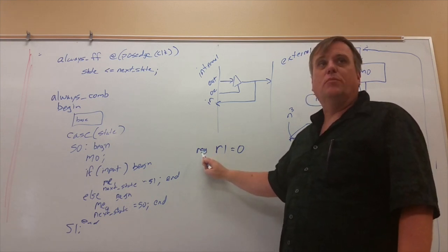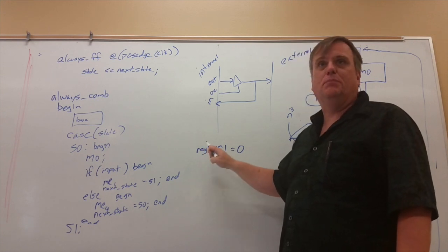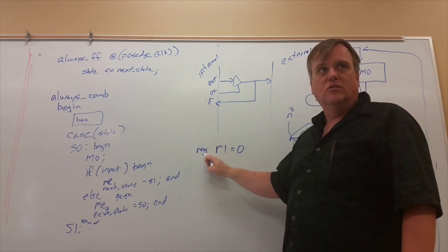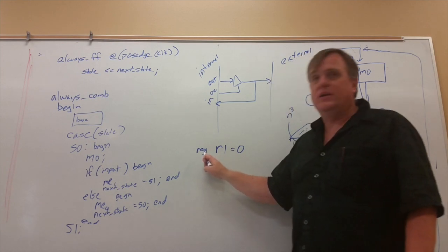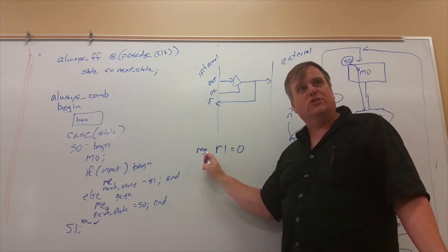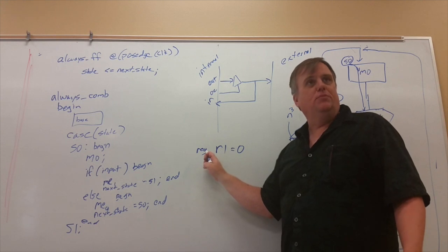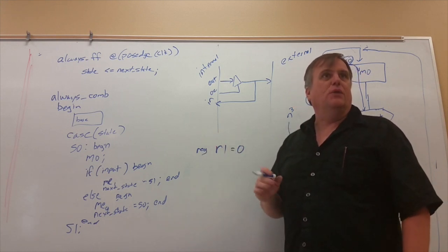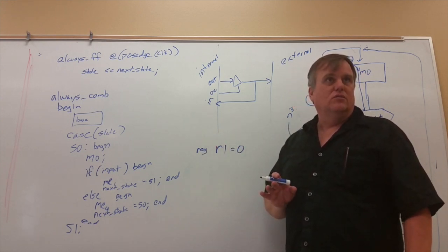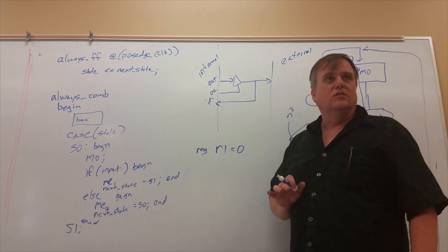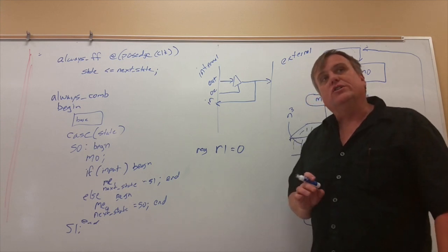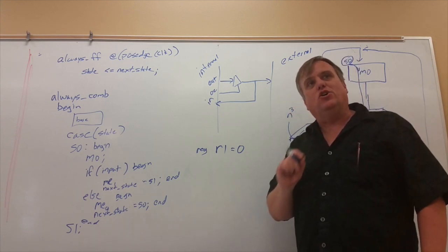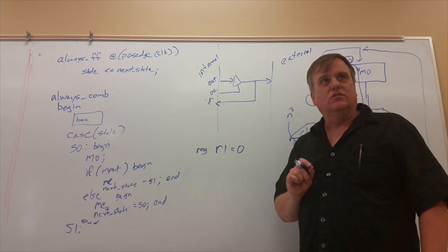Because remember, regs do not necessarily build memory. You can use it in sequential logic. It can become a wire in a combinational circuit, or it could become a flip-flop. How could an FPGA handle this initialization? It has to be different depending on what it synthesizes, right?